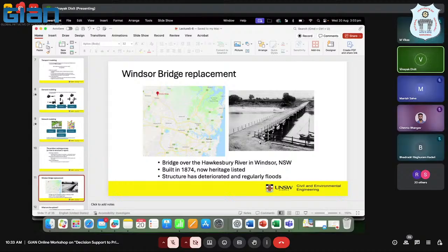So one of the things you want to think about when you're doing a lot of these bridges in your cost benefit analysis is, one, what if the bridge is not there? But the second is also, how many times will the bridge be flooded? If the bridges are too low, they get flooded.